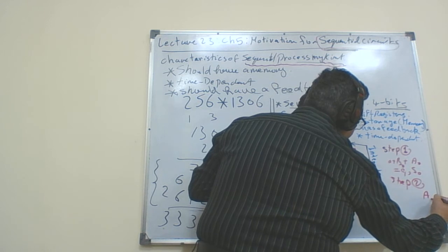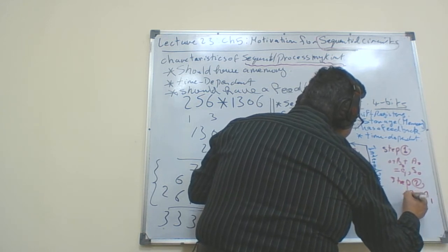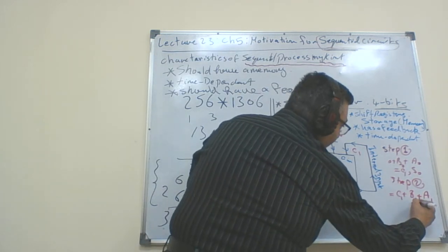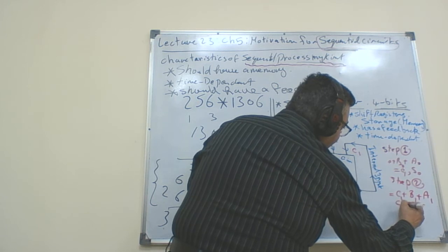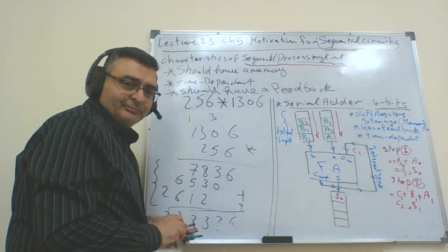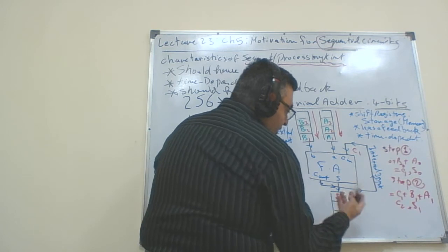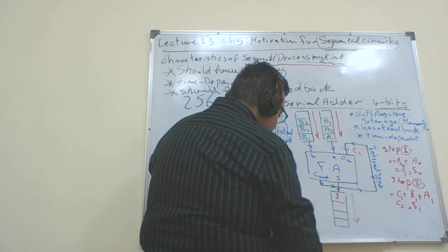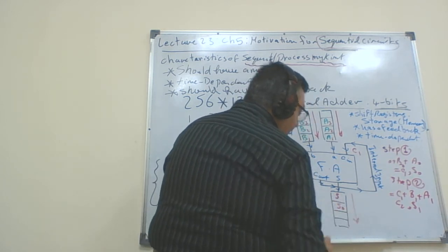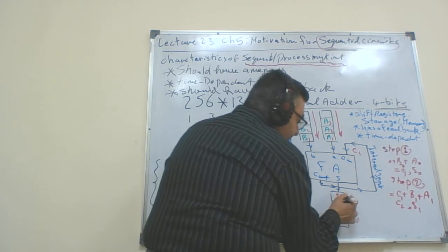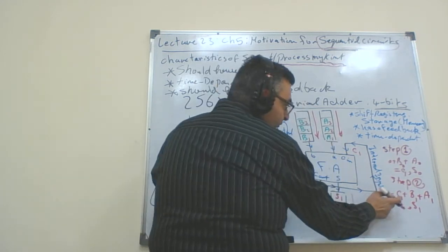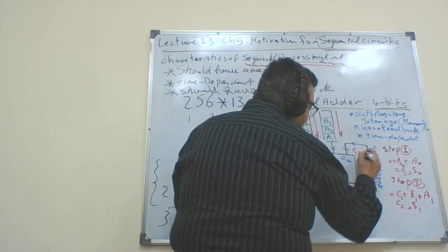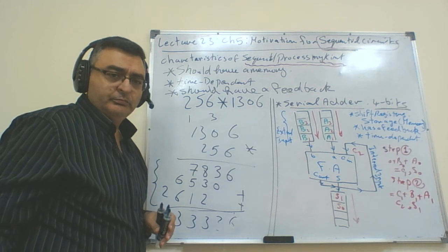When you add A1 to B1 to C1, this will give you the answer S1 and C2. Again, this is a shift register. So S0 produced in the first step will be shifted down one step and will be replaced by S1 from step 2, and also the feedback here will change from C1 to C2.